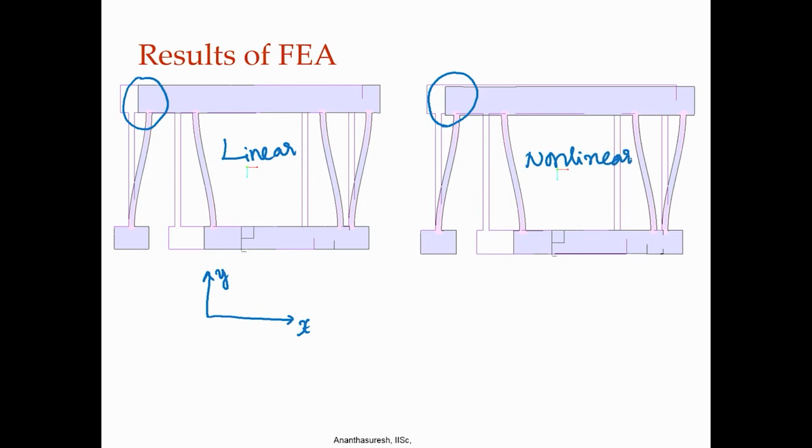It is very important in this particular example because of the reason we go for the folded beam, that is, this one is folded back here like that. The reason is that this platform, if I call it platform 1, is going to undergo in reality both motions, in the x direction and a little bit in the y direction. To compensate for that, we introduce another one, folding this beam back here, so that when this platform comes down, as you see in the nonlinear analysis, you have the other one that compensates. Now here you do not see that. So, this one comes down relative to that one, this actually goes up, these two things cancel each other